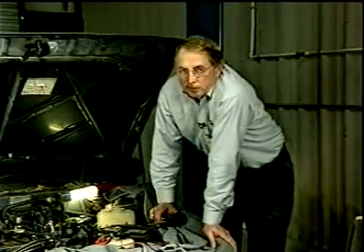Now, in this no-spark, no-start Toyota, we know the pickup coil is bad because, if you recall, the peak-to-peak voltage was less than 1 volt. So we want to make sure that the igniter and the coil are good. What we could do is take a soldering gun and pull the trigger close to the igniter. The magnetic field off this soldering gun will bias the igniter, if it is good, and fire the coil, if it's good. So let's go ahead and do that.